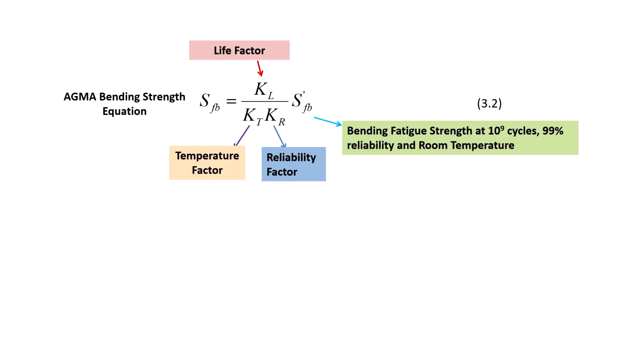This is the bending fatigue strength at 10 to the power 9 cycles, 99% reliability and room temperature. Then the bending fatigue factor of safety is the strength divided by the bending stress.